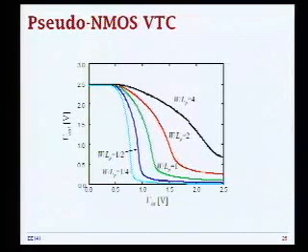As you make this PMOS weaker relative to the NMOS, you have a nicer and nicer VTC because your pull down is strong enough to overpower your pull up and bring the voltage down to VOL, and you have nicer transfer characteristics. So that's the conclusion: this PMOS has to be fairly weak for noise margin reasons.